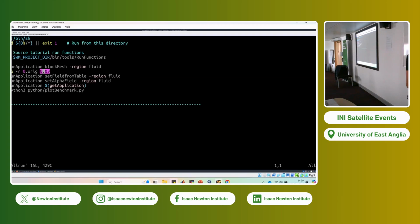So we want to start our simulation from this point here, and we are just going to tell OpenFOAM to call the 0 folder, call it 0.03, so that then it's easy to compare the result with the analytical solution. Otherwise we should shift it, but this way is a bit easier.